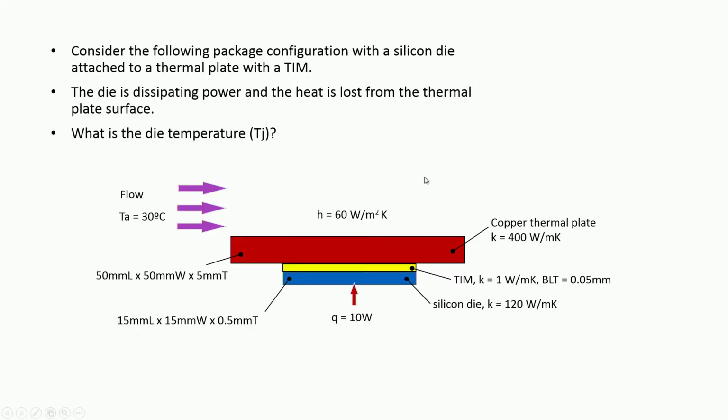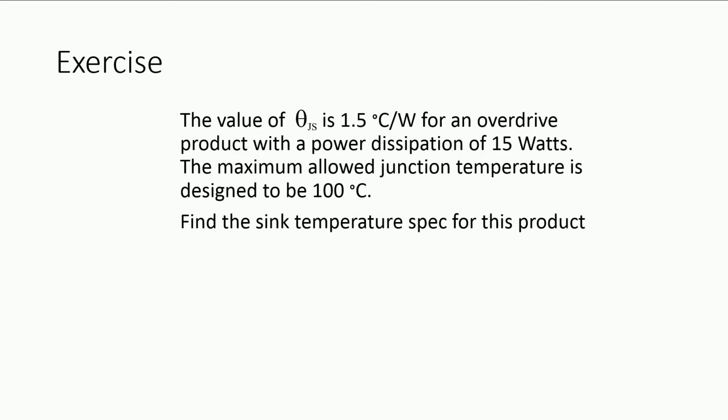You will also see, maybe as just a side note, it turns out that the potential that drives the flow times the flow is energy: voltage times current, clear, or pressure drop times volume flow rate. Okay. Over here it is a little different, because the flow itself is the energy, which is Q. All right. Even in solid mechanics, force times displacement, or stress times strain, is the specific energy. Okay.